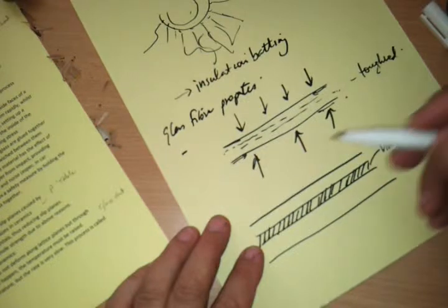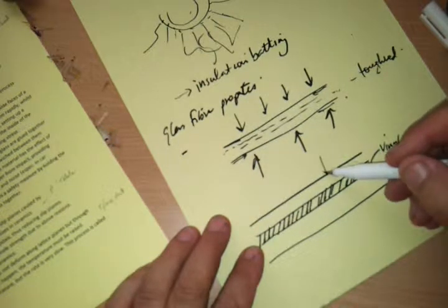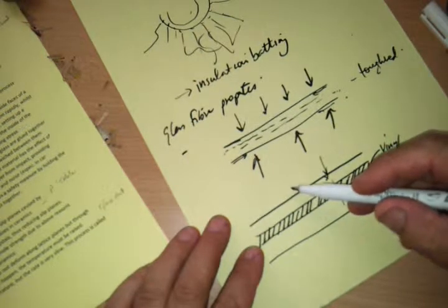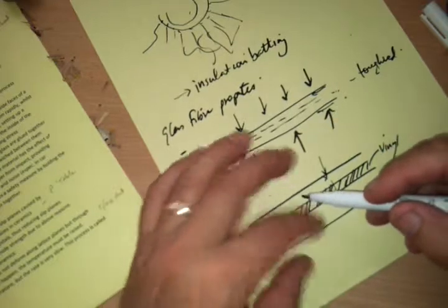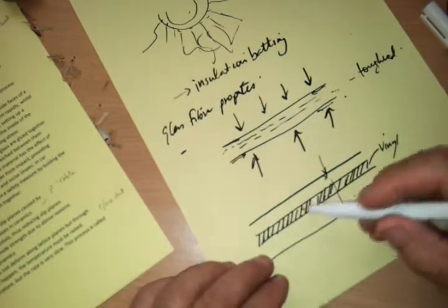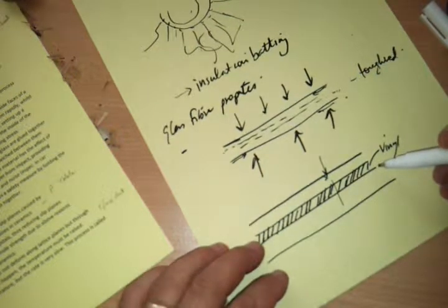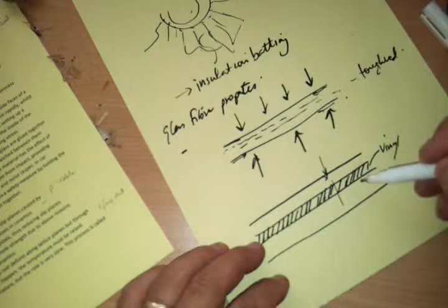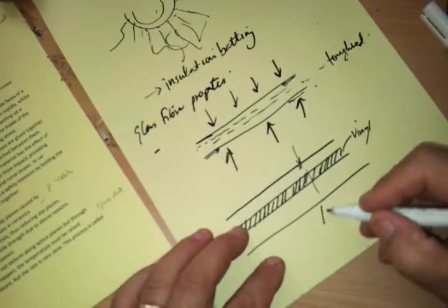It also means that in windscreens, where this is particularly used, if there's a stone chip or a crack that's created, it doesn't go all the way through the glass. Or if there's a large dent or smash, the glass doesn't fragment into shards and hurt somebody. It's glued together using this polymer sheet which lies in between the two sheets of glass. So that's called laminated glass.